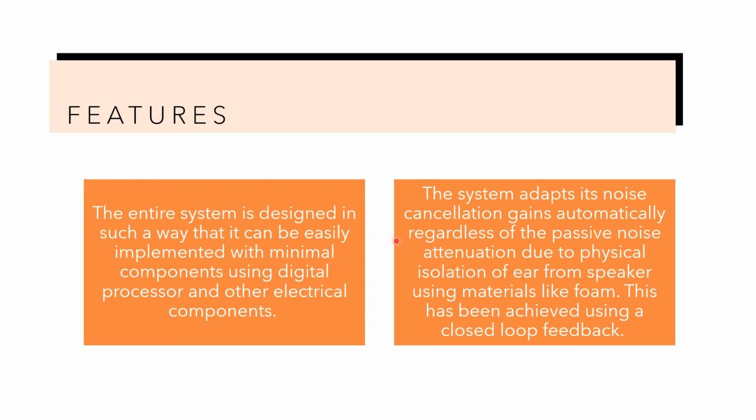Here I would like to point out some assumptions which we made while making this system. We have assumed that the time it takes for the DSP to calculate all these gains is equal to or smaller than the time it takes for the noise to reach from the noise microphone to the feedback microphone. Also, if the processing time is lesser than the time it takes the sound to travel from the noise microphone to the feedback microphone, we can just add a delay block based on our processing times.